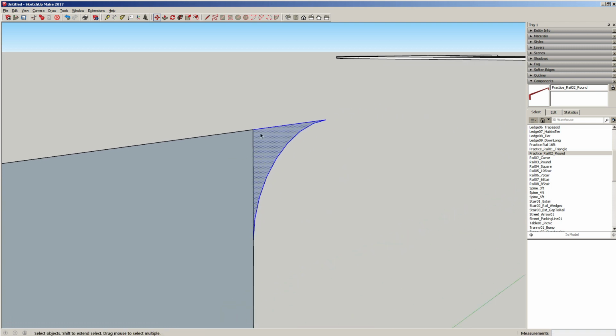You're going to right click, flip along. I think it'll be green direction. Right? Now we're going to do copy again. Hold C, click, snap back to that corner, and now you can double click this face, delete, click on our canvas, delete.